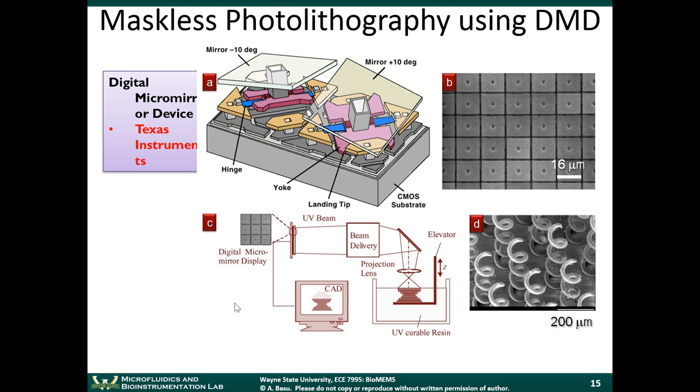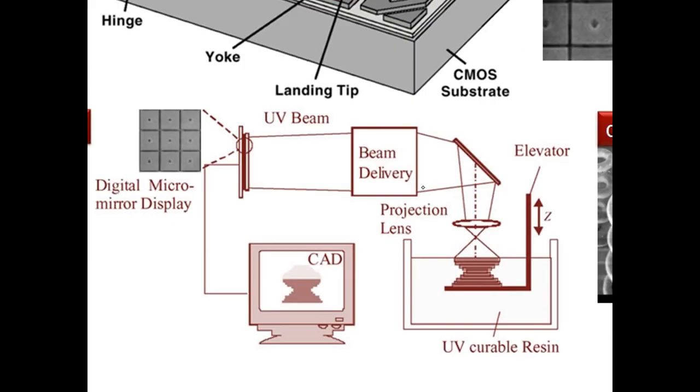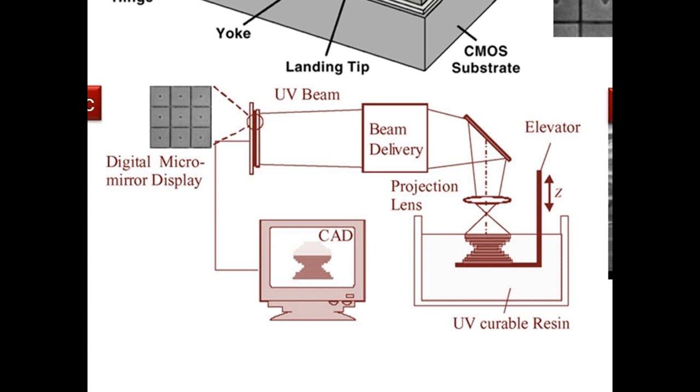Micromirrors, as you know, the idea is that you have a beam of light that's pointed at the micromirror. Now this schematic here is a little bit simplified. What you'd actually have is a light source somewhere around here, and that light source would be pointed at the micromirror array, so the light would go something like this.